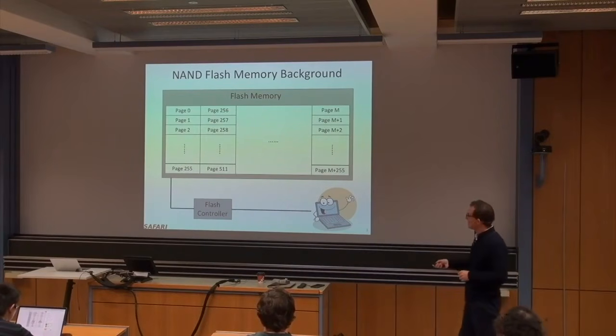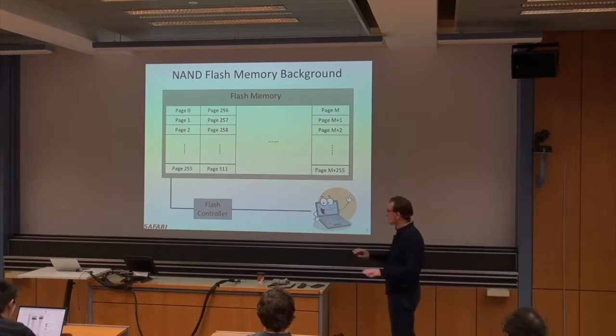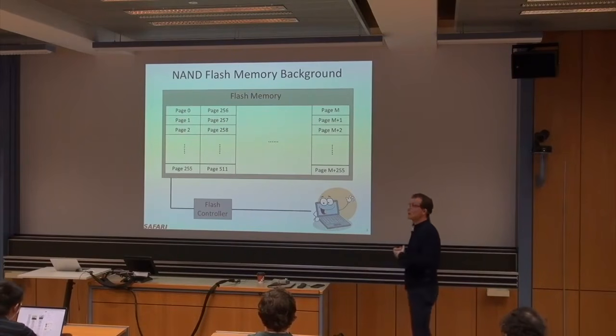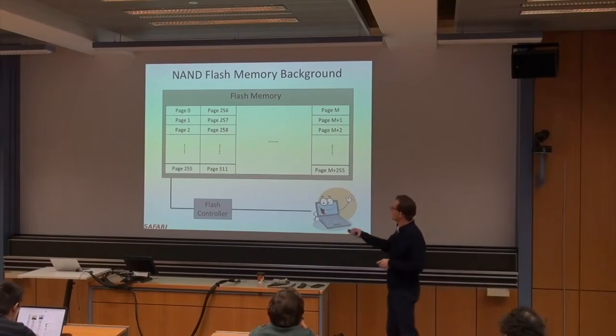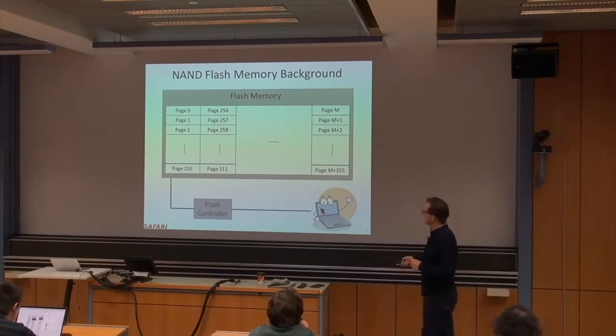So remember, erase at the block level, such that everything becomes 0, and then you can program at the page level. That's called programming, or writing. You write at the page level. And then you can, of course, read at the page granularity as well.